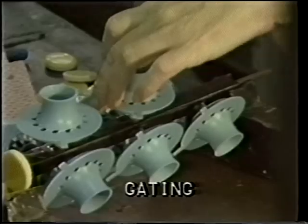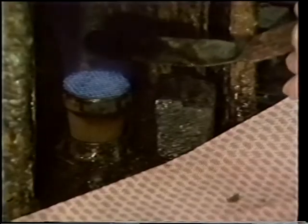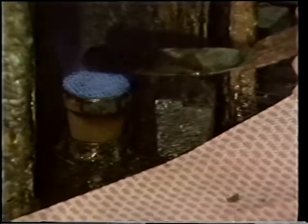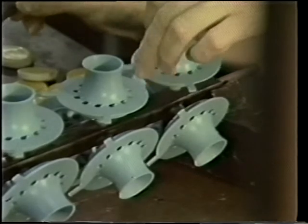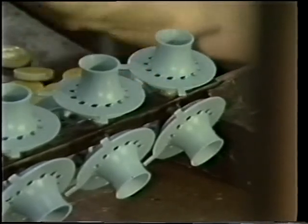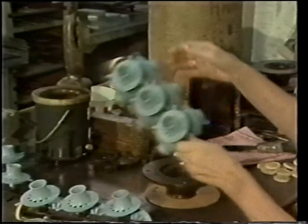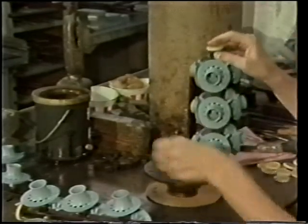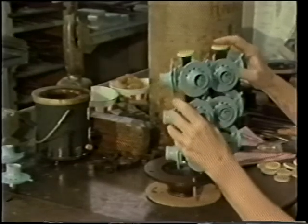Several of the wax patterns are attached to a central sprue with runners and gates by means of heated tools and melted wax. This allows a number of parts to be produced from a single mold. In some cases, several pattern pieces can be united to form a complex single pattern that, if made in one piece, could not be withdrawn from a master die.